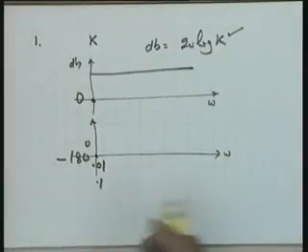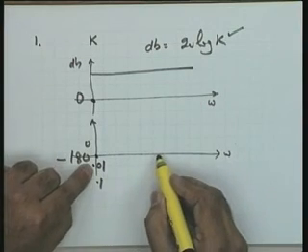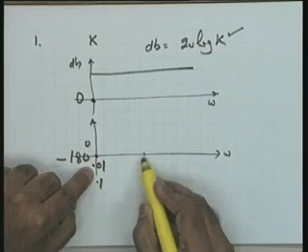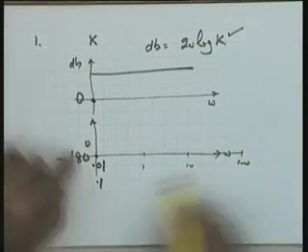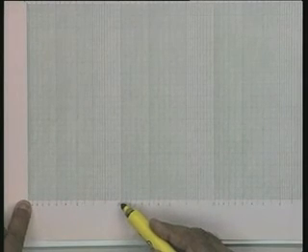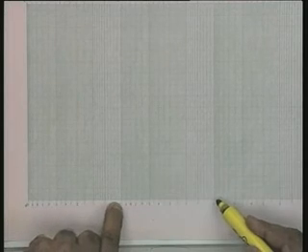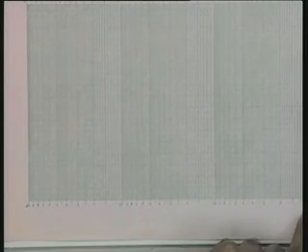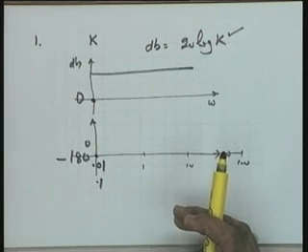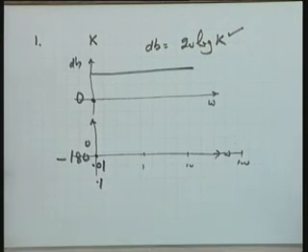So you see that if you take 0.01 and you find the maximum, as you will see shortly, if 0.01 is taken, then 1, 10, 100. 100 will be the maximum which can be seen on this graph sheet, please. 0.01, this is a multiple of 10 as I am going to explain to you. So this will be 0.1, another multiple of 10, it is 1, and another multiple of 10, it is rather 10. So it means the maximum you can view in this particular case is 10 radians per second, and therefore 0.01 may turn out to be too low. You may not be able to see your high frequency range adequately.